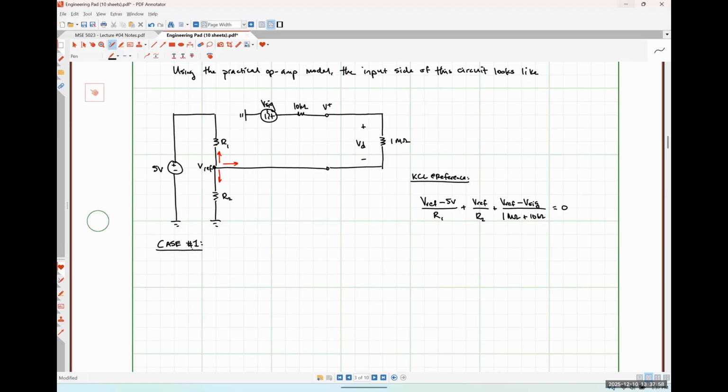So in our first case, we're going to say that R1 is 2 mega ohms and R2 is 3 mega ohms. As a sanity check, do these resistor values give us the voltage divider ratio that we're looking for? 3 over 2 plus 3 is indeed 3/5. So I would say yes.